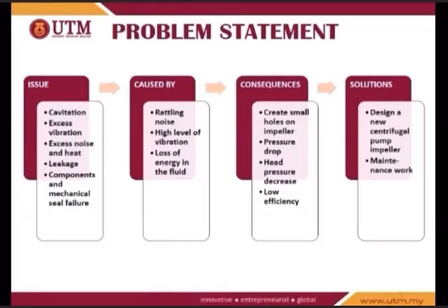So these are the problem statement for this study, and the issues are cavitation, excess vibration, excess noise and heat, leakage, components and mechanical seal failure, which is caused by rattling noise, high level of vibration, loss of energy in the fluid, and as the consequences, it creates small holes on impeller, pressure drop, head pressure decrease, and low efficiency.